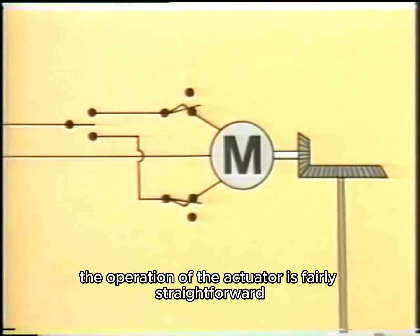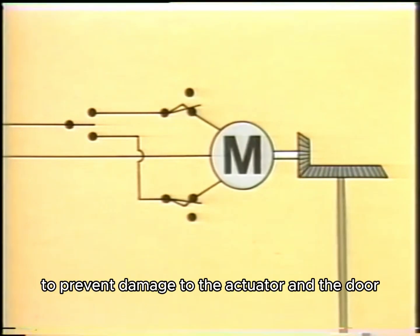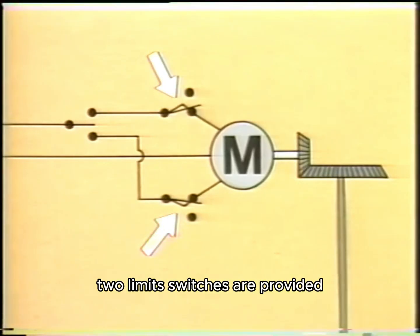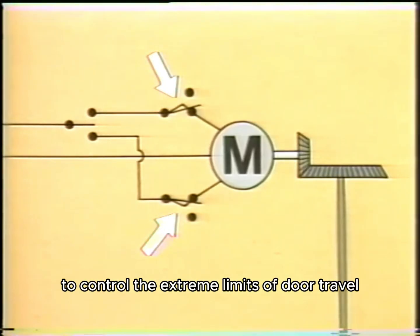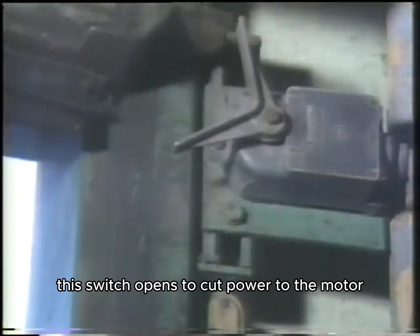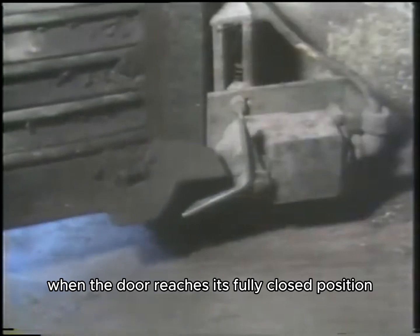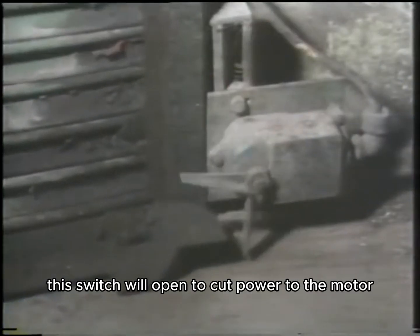In principle, the operation of the actuator is fairly straightforward. An electric motor drives a set of gears which in turn open and close the door. To prevent damage to the actuator and the door, two limit switches are provided to control the extreme limits of door travel. When the door reaches its fully open position, this switch opens to cut power to the motor. Likewise, when the door reaches its fully closed position, this switch will open to cut power to the motor.